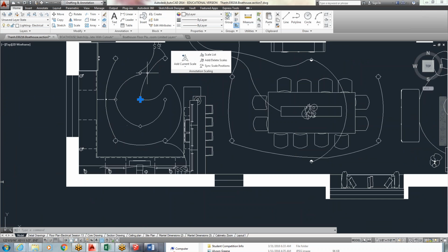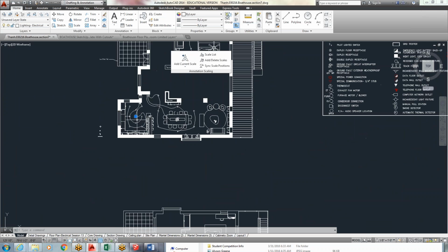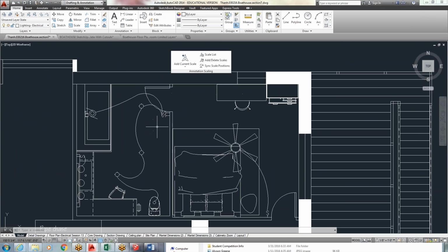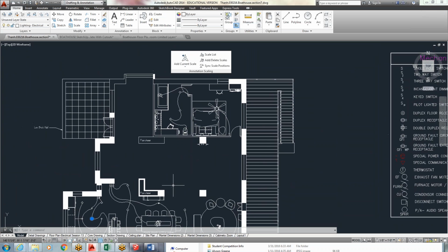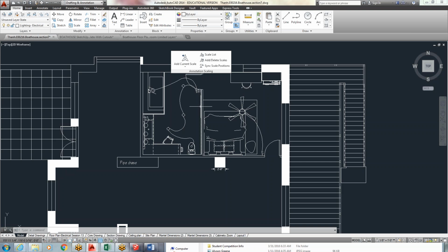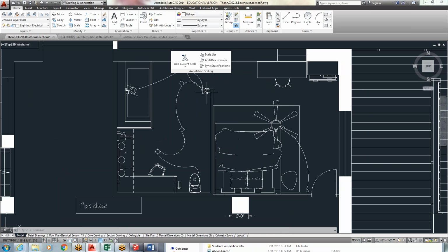Let's talk about, we talked about the switches, why I have S3 here. And here I just have single pole switches, and here I have a single switch too. So you're going to be working on these plans and creating either your own lighting layout and connecting your lights. Some other thing that hangs students up is for a single switch, even though these are 6-inch can lights and this is a 4-inch can light, the single switch can have different types of lights on it. It just notes what you're turning off at once.